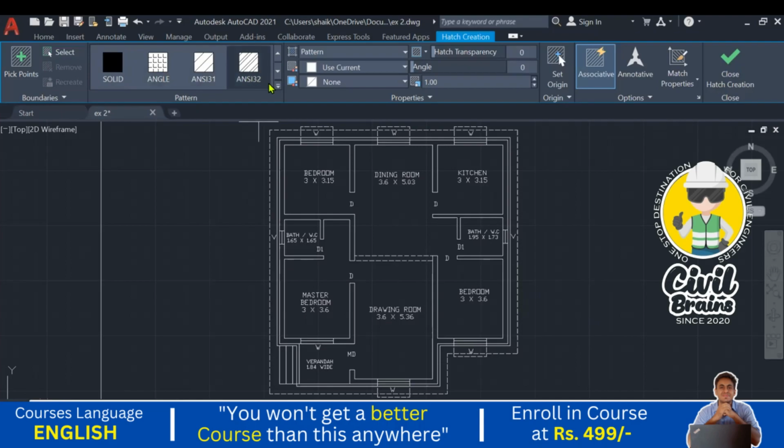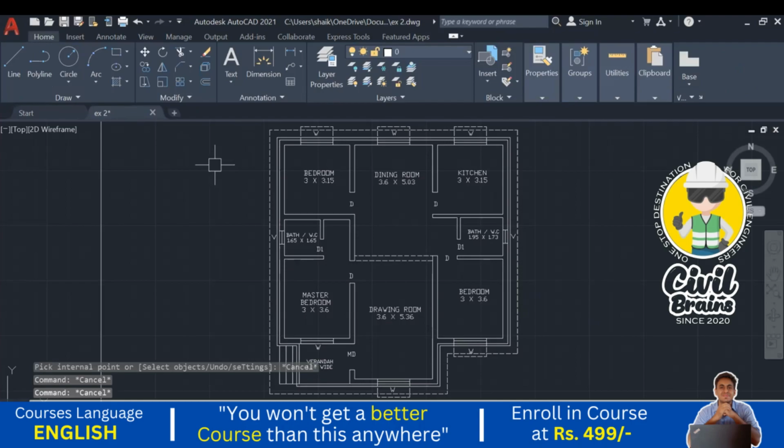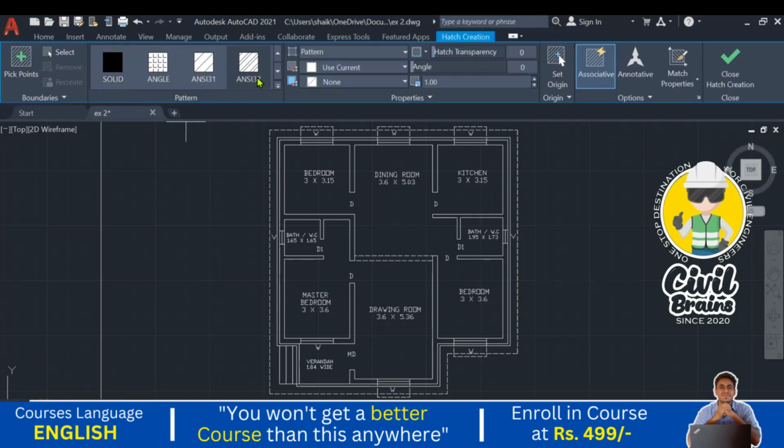Okay, so which hatch are we using for the plan? So for the plan we are using this hatch ANSI 32. Okay, that is for the plans, or we can say for the burnt brick masonry or for the superstructure. So what is superstructure? We divide a building structure into three categories. One is substructure, one is superstructure, one is roof. Okay, so for the superstructure we are using this hatch.